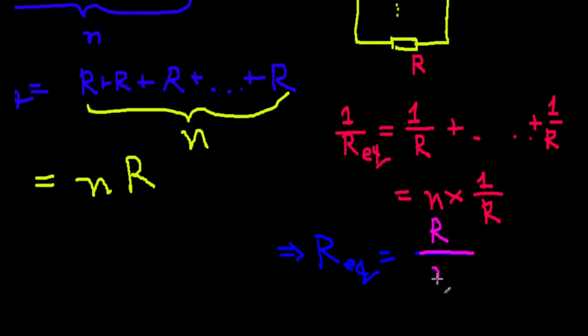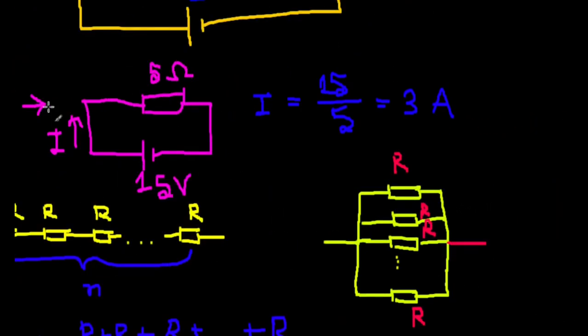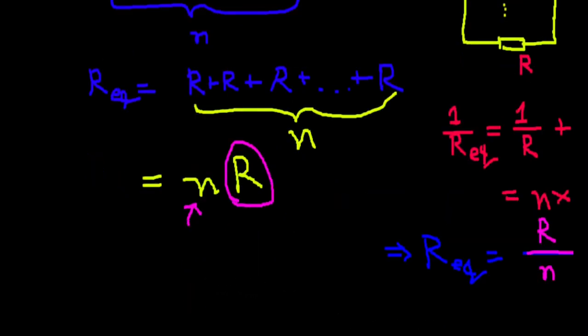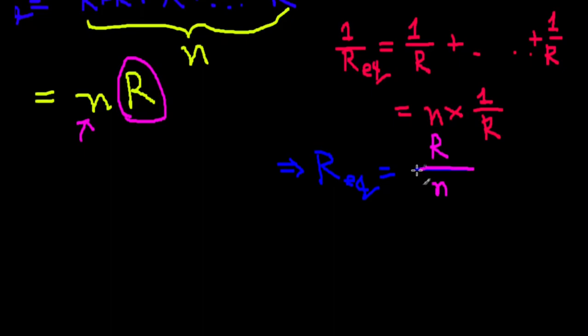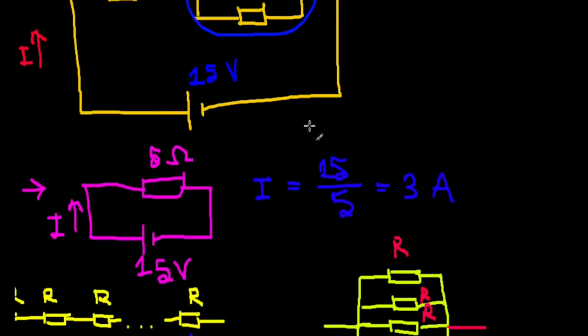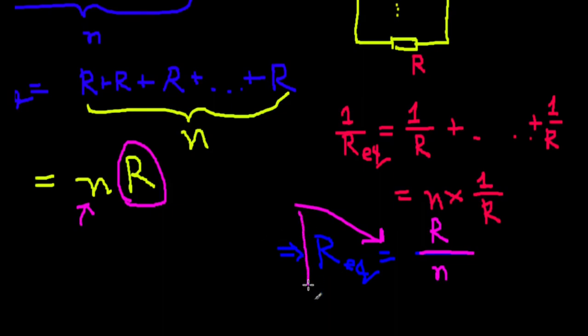So just something interesting, following the trend that series and parallel resistors have properties which are flipped around, or opposite, you could say. Here, if you have n resistors of the same value in series, you scale up the resistance of the one resistor by your number of resistors. And here you divide the resistance of one resistor by your total number of resistors. Just something that's interesting to see. And to be honest, when you keep dealing with these mixed resistor problems, you instinctually get the habit of using this one. This one's pretty obvious, but you also instinctually get the habit of using this one.